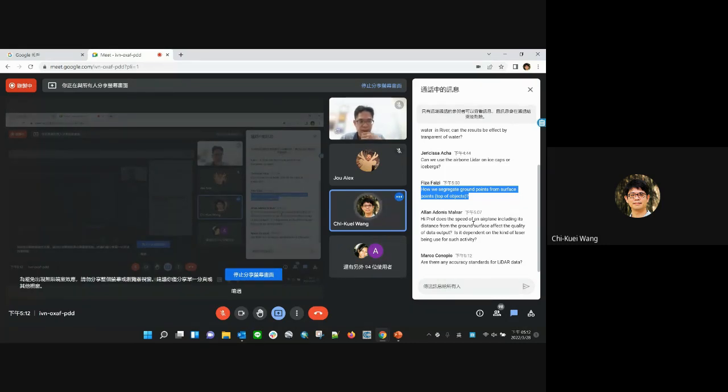For those of you who may have experience with image classification, you should know that the automatic classification is not always good. Same thing for LiDAR. So if you want a very good result, such as those examples I show you in my slides, then you definitely need some manual editing to make it a very perfect surface.